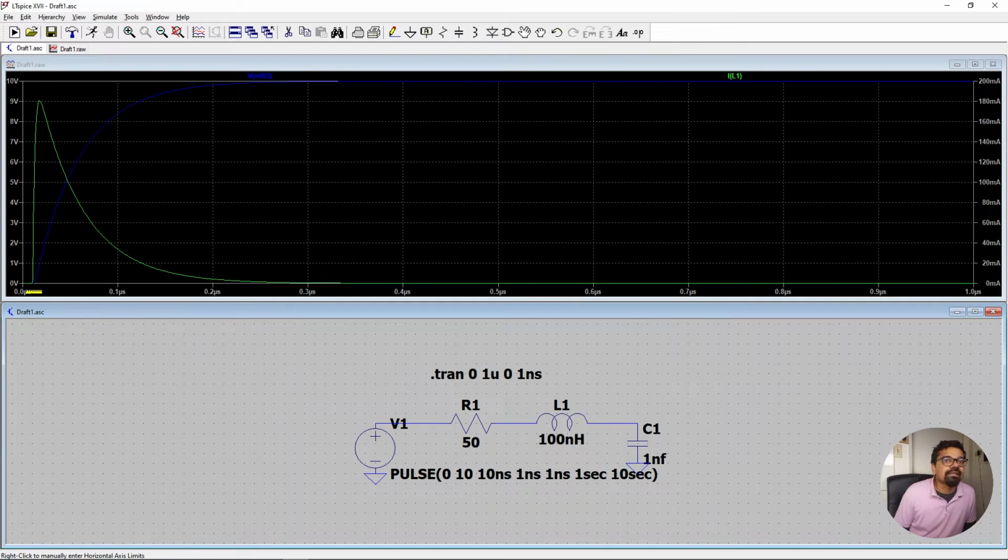And this says that we're kind of like an open circuit, and once there is no more transient, the di/dt has died off, so L di/dt, di/dt is almost 0, so the voltage across the inductor is also 0. That means it becomes a short circuit. So you can think about it that way.